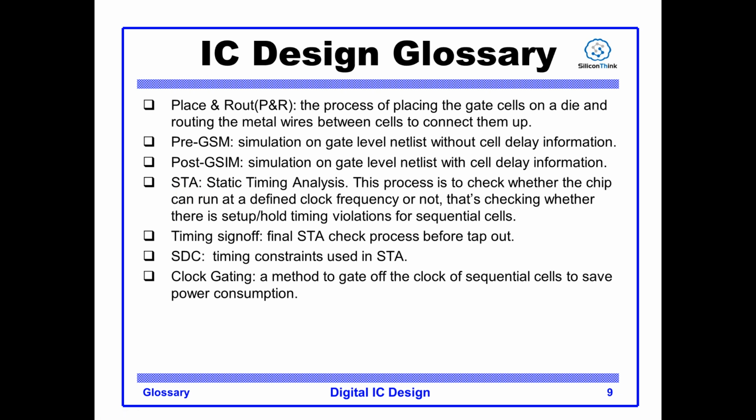No, that's not accurate. Basically, it depends on your design, but the STA tool will give you the assurance. STA analysis will tell you whether your chip can run at that frequency or not. Okay, timing sign-off. This is the final STA check process before tape-out.